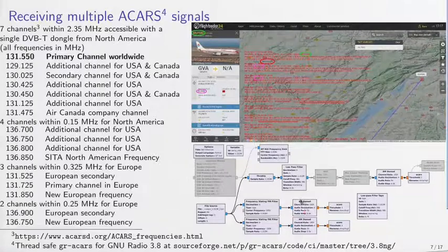So here we have an AM demodulation centered on each frequency channel. We see here that we centered on 131.7 megahertz, and we have 2 frequency offsets, plus 200 and minus 100 kilohertz, to analyze the 2 channels separated by 300 kilohertz. This allows us to collect all the ACARS messages of the planes flying in the area.